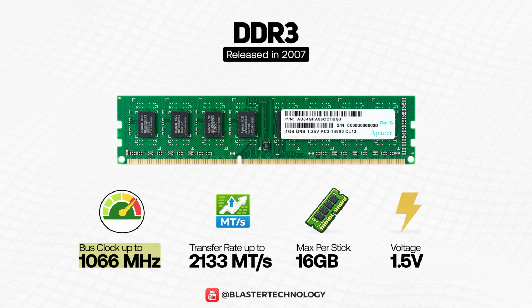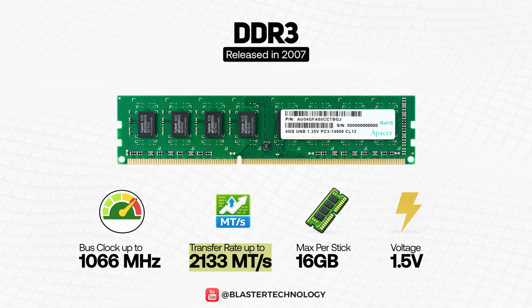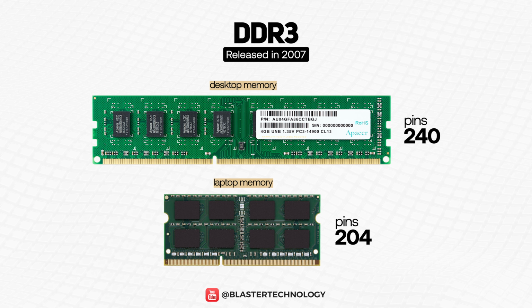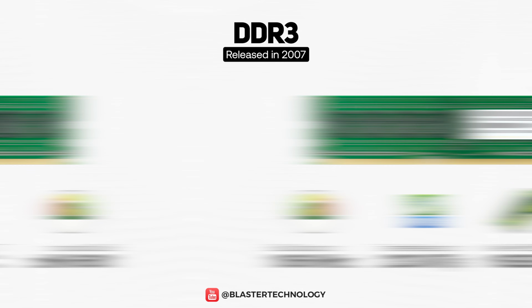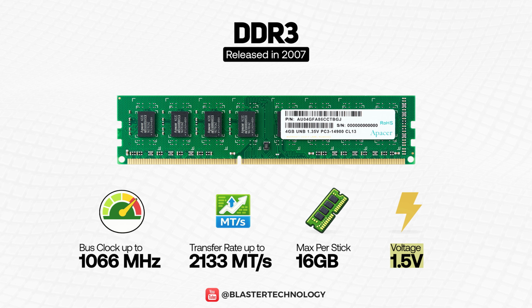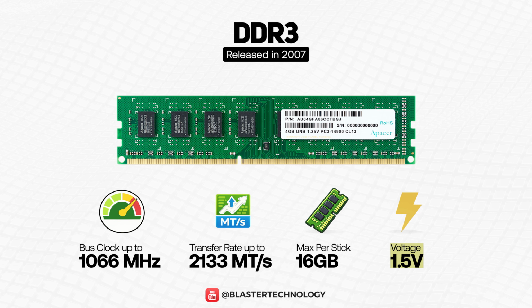With a bus clock of up to 1066 MHz and a data rate of up to 2133 megatransfers per second, DDR3 delivered a significant performance improvement. For desktop systems, DDR3 modules use 240 pins, while laptop modules use 204 pins. The maximum capacity reached 16 GB per stick, and the operating voltage was reduced to 1.5 volts, helping lower power consumption and improve battery life on laptops.